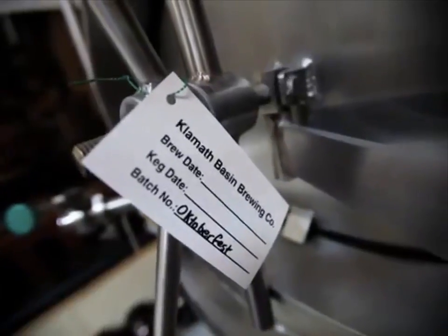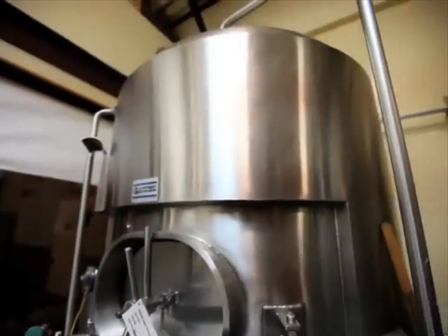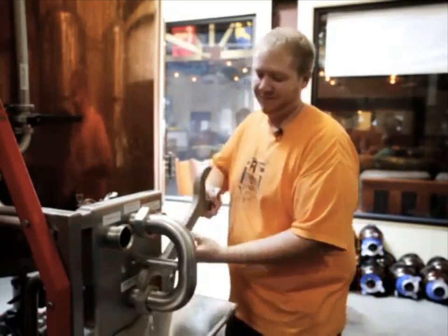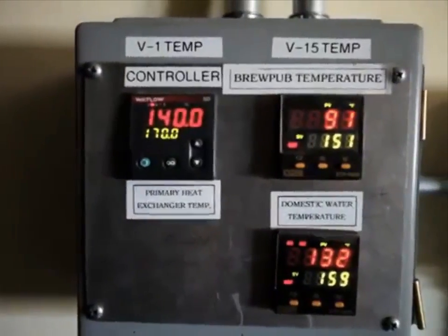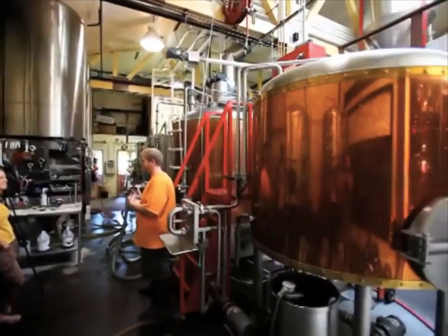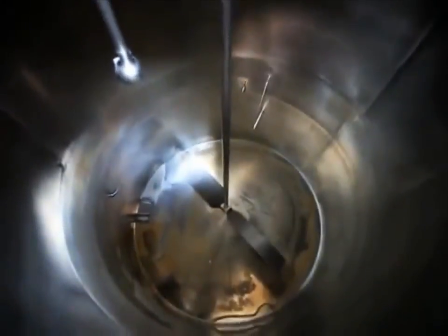The geothermal energy is used in the mashing process. That's when you're combining your grain and hot water. It rests at that temperature while enzymes that are present in the malted barley convert starches to fermentable sugars. At the end of this conversion, it's pumped into the lauter tun, which has screens on the bottom, and filters the liquid, which is called wort. At that point it is boiled between an hour and 2 hours, and that's when the hops are added.